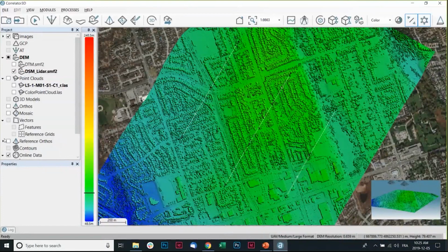So if you want to do so, you'll have to bring in the intensity layer as a reference ortho in your project tree. You could add the little plus button here and then bring a folder where all your orthos, in this case the intensity, are saved. And the other element that you need is that you will need to have a DEM loaded.